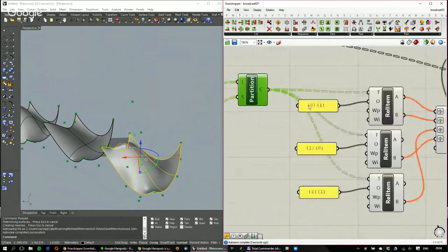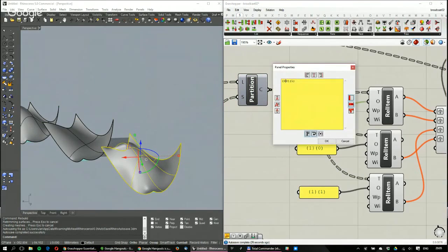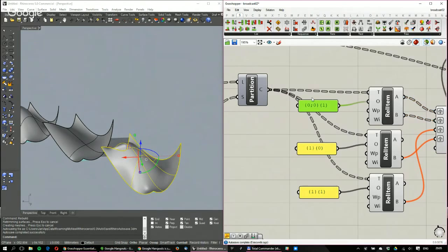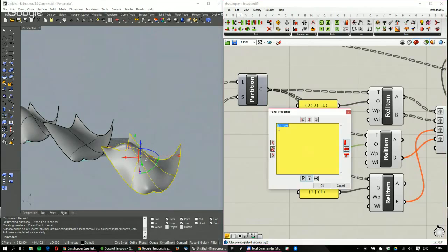work because they only calculate with one level of the data tree, and now I have two. So the first one is defining with which geometry I'm working. The second one is the U, or I don't know if U or V direction, and those four items in each one are points in the V direction. So basically, if I want to define a relative path, for each one I have to say that I want to work only with my geometry, so it should be always a relative offset of 0 here.